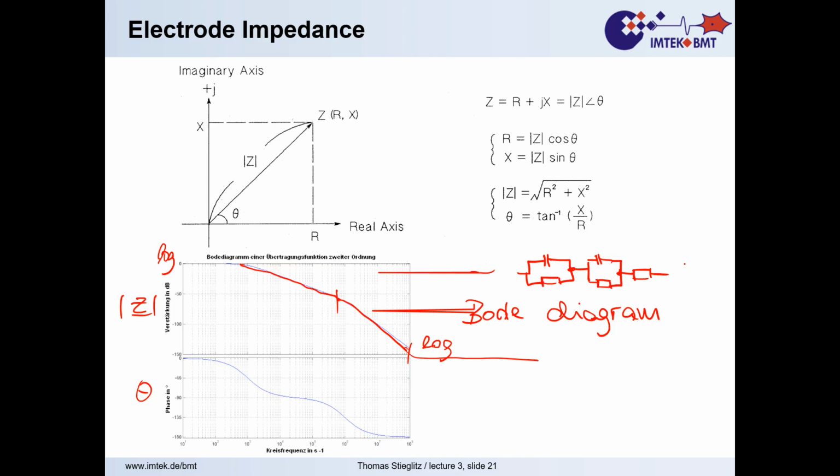I just want to complement that. And we can also draw information out of the phase. This is a complex value, the impedance. So we use for the impedance a sine wave that we apply and measure the outcome. The outcome, if we do it correctly, is still a sine wave, but may be phase shifted and attenuated in magnitude. And we need then either the magnitude and the phase to get the full information. This is done by the length and the phase angle.